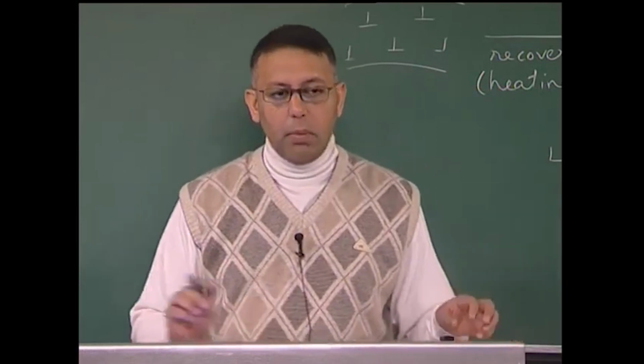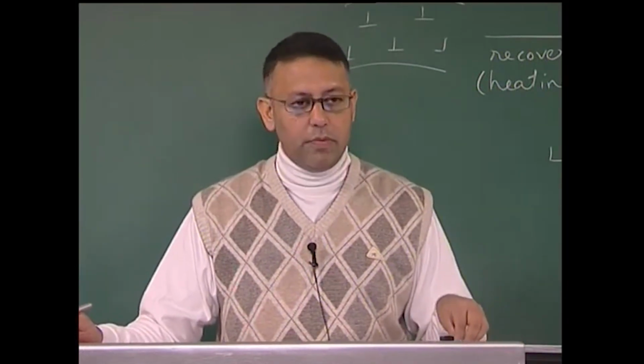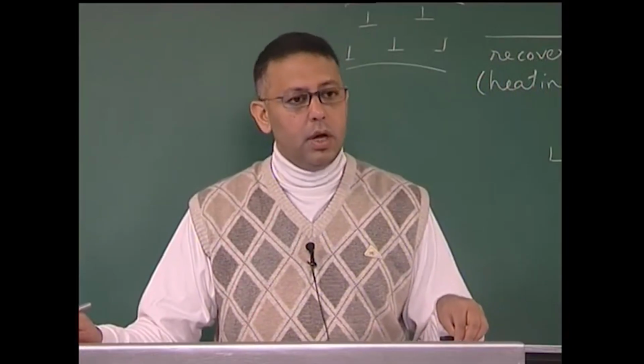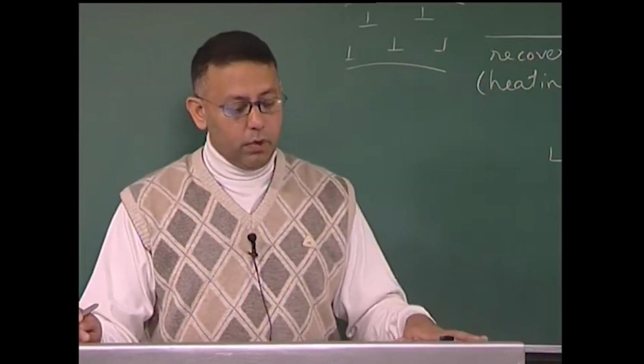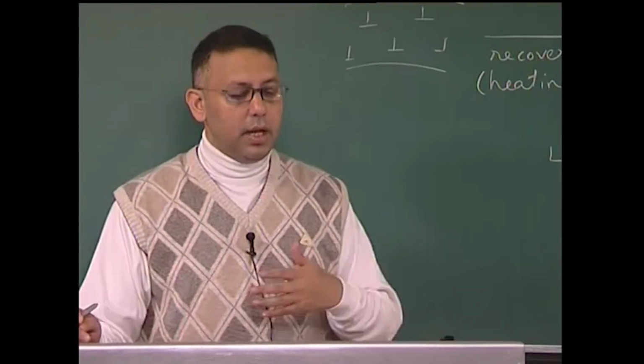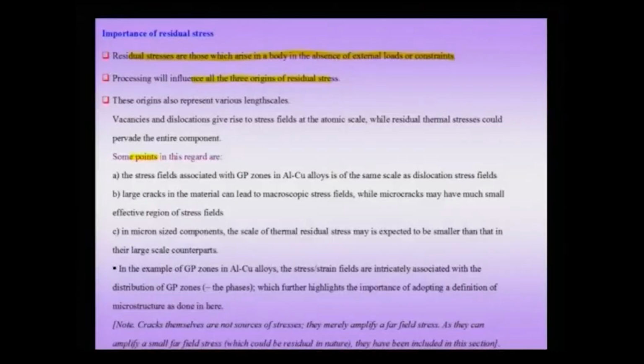The length scales we are talking about range from that at which a vacancy exists, to the scale of precipitates and dislocations, to the scale of the entire component. So, we have to remember that residual stresses can pervade the entire gamut of length scales available to the material. Okay. So, we have to note some important points in this regard.